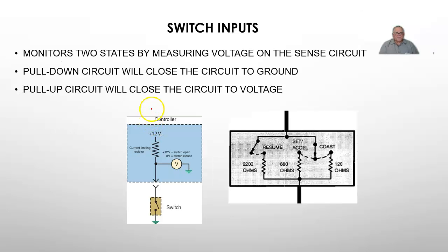The simplest of our inputs that we're going to be looking at is a switch input. This can be that the computer monitors a circuit that it's not controlling. For example, if you had an alarm system, you had an older vehicle that you open the door, the interior lights turn on, you close the door, the interior lights shut off. There's a switch on the door. The computer monitors that switch. It sees either voltage high or voltage low, depending if it's ground side controlled or not.